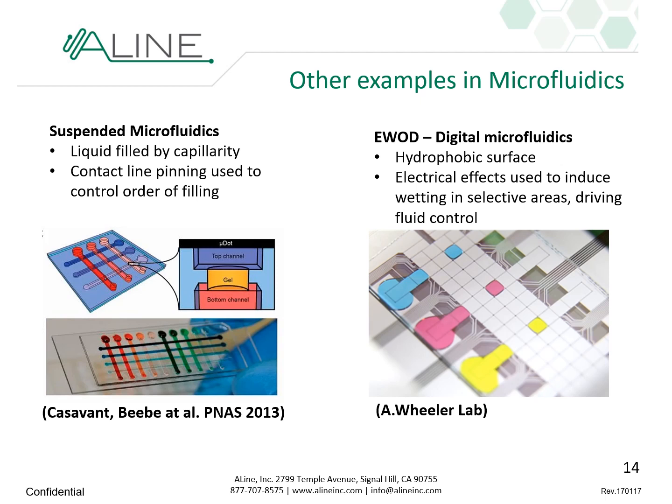Other examples in microfluidics that really rely on wetting, I'm just showing two here, but there are many more. One is a very interesting concept that was pioneered by Casavant and Beebe back in 2013. It's suspended microfluidics. The liquid is filling by capillarity, but they're using contact line pinning, so the fact that the liquid doesn't really like to go through corners or sharp edges, it typically gets stuck.